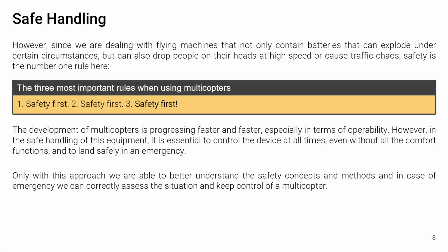With the development of the mechanically simpler so-called brushless motors, more power can be provided with the same size compared to brushed motors. Multicopters are usually operated with batteries that supply DC voltage. Here, the lithium polymer battery, also known as LiPo, is very often used. Brushless motors are electric motors that can operate with direct current and are driven by permanent magnetic fields. This makes the energy supply much easier.